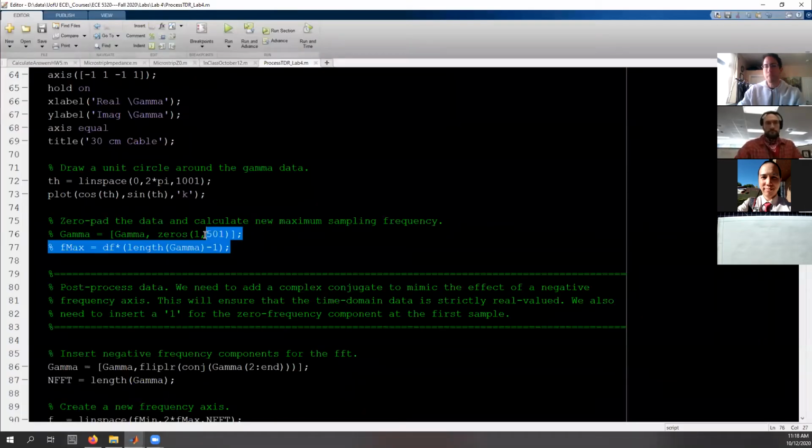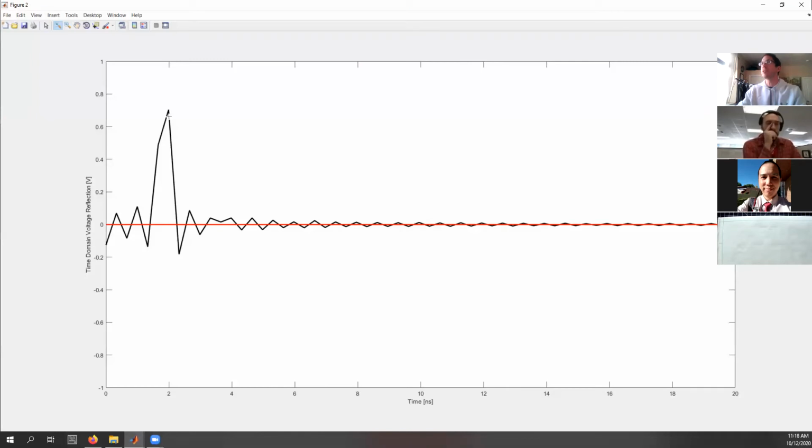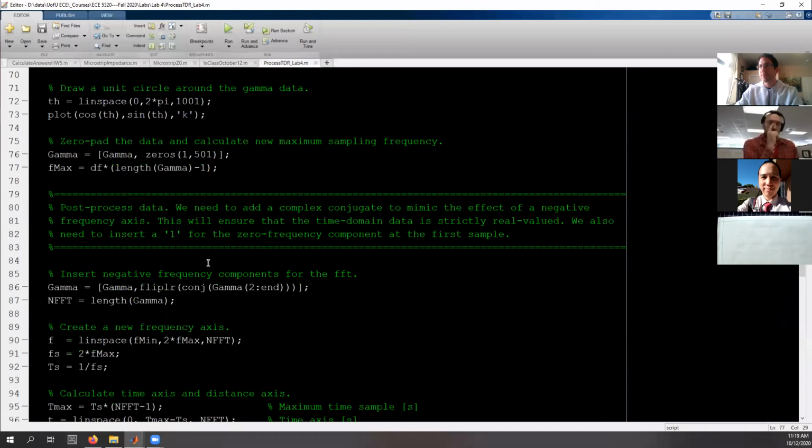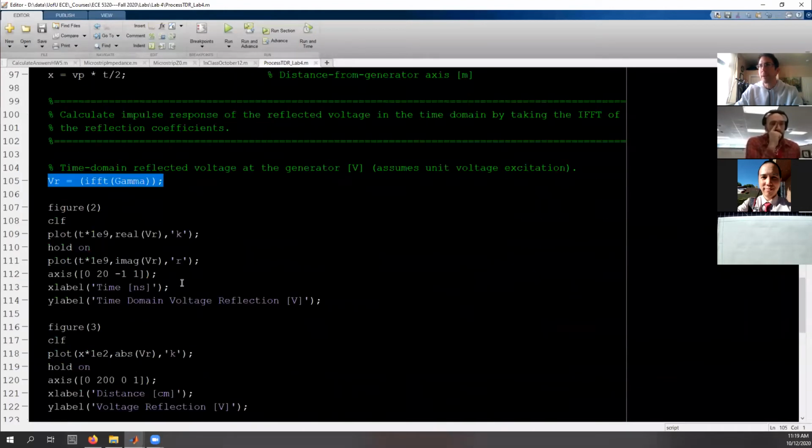So when we do the zero pad, all it's going to do is essentially play connect the dots. It's also going to reduce the scale here, so you may have to do some normalization after the fact. That's just a quirk of the FFT, that the magnitude of everything is going to be scaled by the number of points. So this peak is going to shrink. And I think there's a way to compensate for that, but I haven't actually done that.